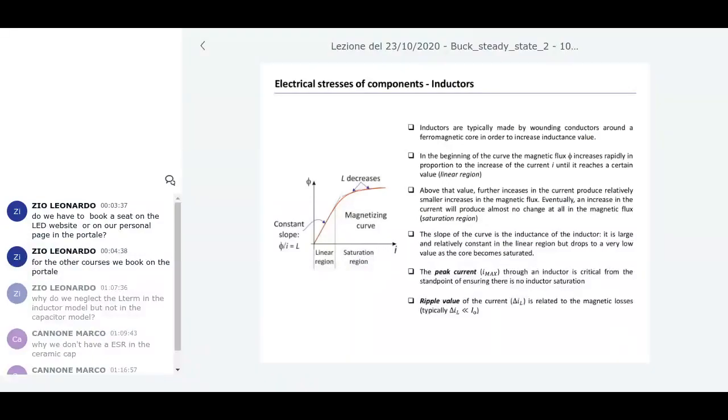We chose this inductor based on operating conditions in CCM, so we have inequalities, and on the basis of these we can choose the inductor. What about all the other components? Let me discuss a little bit what kind of parameters I have to compute to fully understand how to choose all the other components.